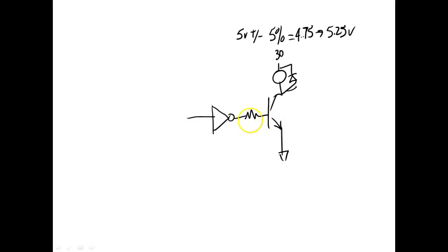Well, we got one of two options. We could take the output of the gate, just say an inverter, and we could feed it into a bipolar transistor. And good gracious, guys, we could put maybe 30 volts up here, and we might be running a relay. Okay. But the only thing this guy can really do is turn this thing off.